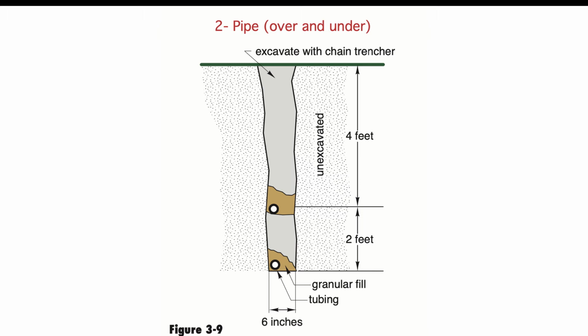Obviously, the soil conditions are going to dictate the heat exchanger's capabilities of transferring BTUs. A sandy or a gravelly type of mixture of soil is going to have very poor conductance versus a system that has tightly bound clays, and moisture also plays a key factor in the ability of these heat exchangers to transfer heat into and out of the loop field.